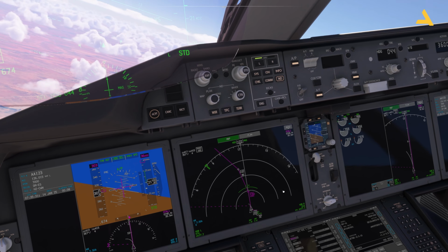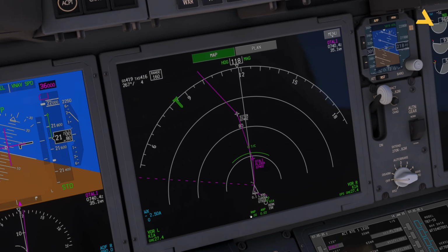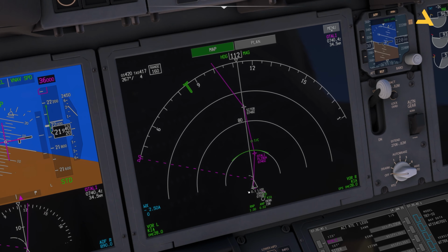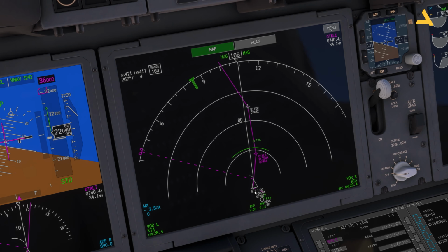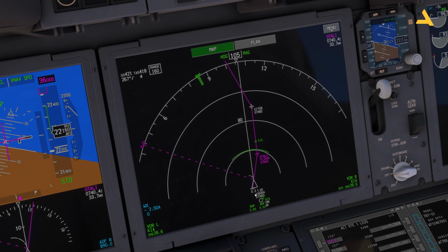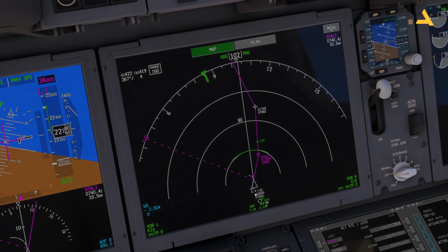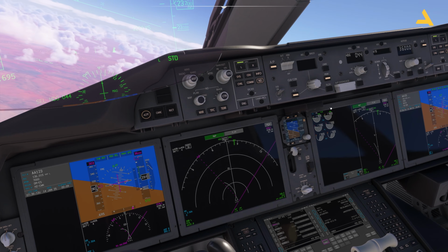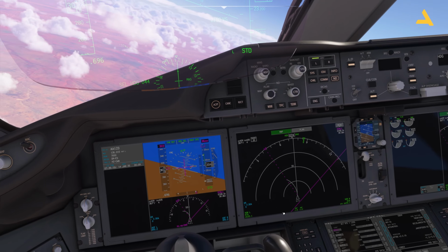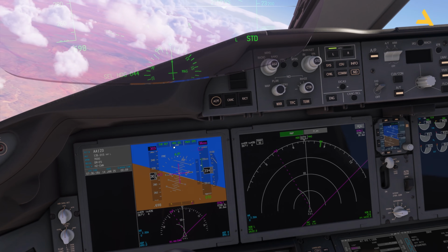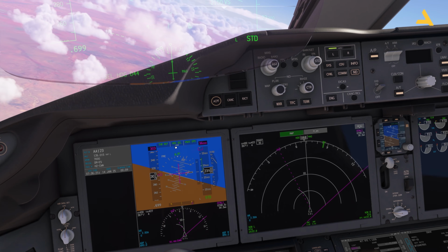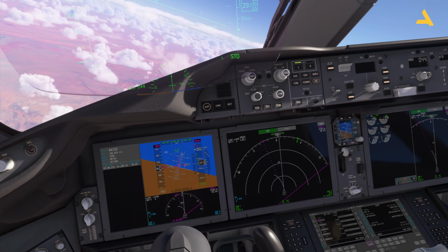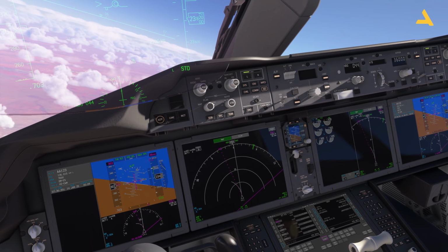And let's see what happens. The deflection is even shown over here. It's 0.1 nautical miles towards the left, and it will keep on increasing as the plane keeps on going towards the left side. 0.4 towards the left, 0.5, 1.7. Now if I press LNAV, you will see that the plane will not start to follow this flight plan. Now the active mode is the heading select mode for the navigation, and LNAV is armed as it's appearing in the white color. So in order to follow this flight plan again, I will just move this